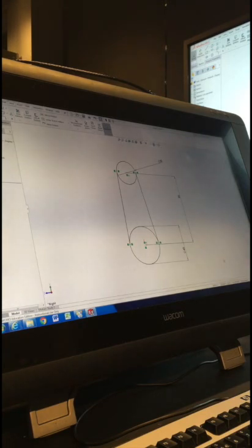So you can't do it with the dimensions we want. Turn it off. And then grab that center point. Hold Control. Now, what's the difference on this dimension here? It's grey. It's not an actual driving dimension. So you delete that. Just make another one. So this grey dimension here is not going in here.